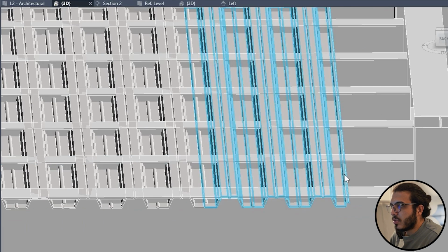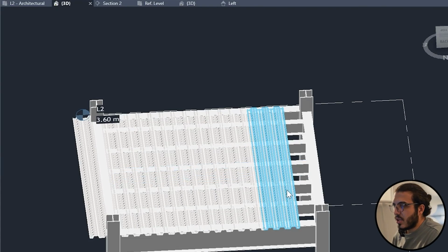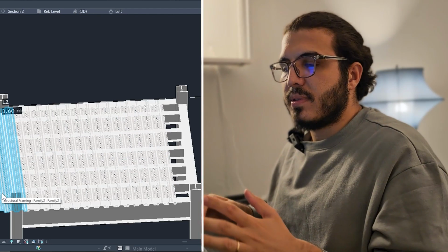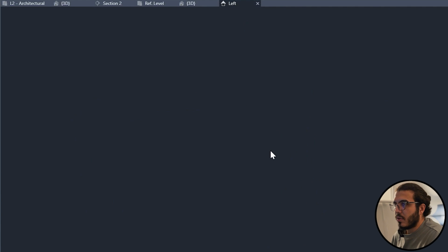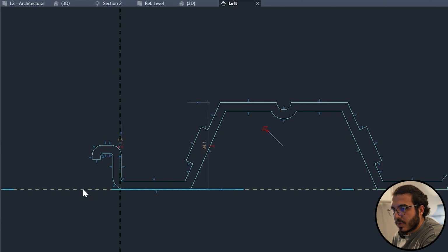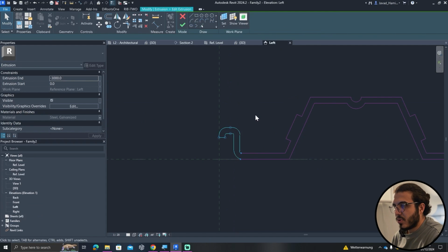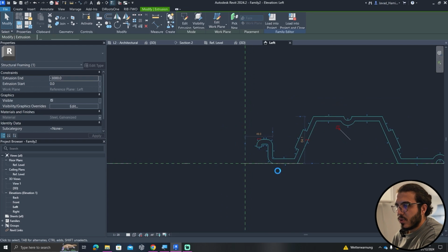Right now, these parts are empty, and I think the reason for that is that this part that we've created is not equally divided, and when Revit divides this, it can't place other ones in here. We can fix it easily, but let's fix that one first, which is this. Let's bring it a little bit to the right, maybe, go to the profile in here and select these parts and bring it a little bit to the right. Now I think it will work. Click on finish and bring the whole thing to the left.